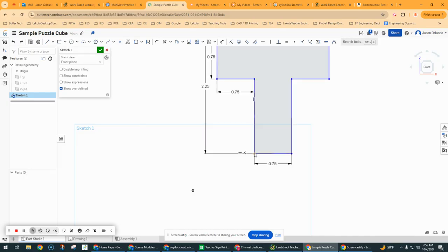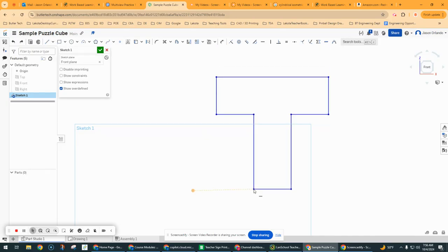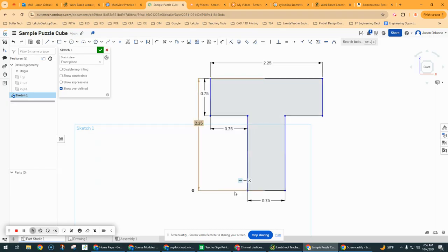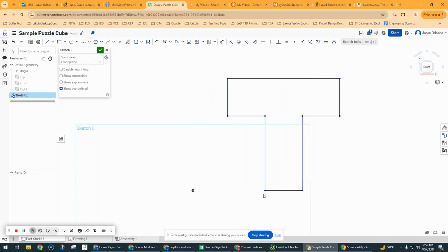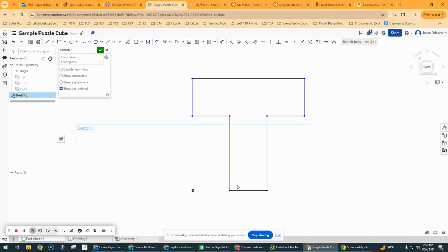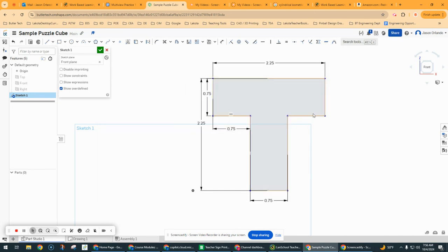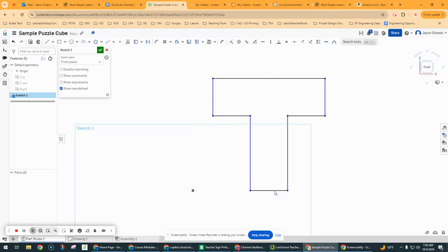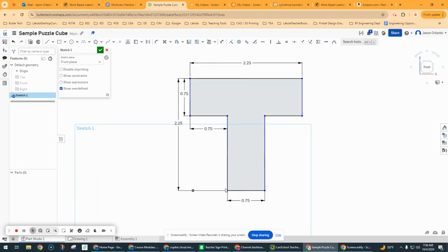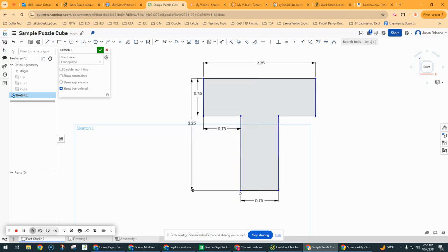Okay, now if your sketch maybe was already constrained a little bit, but not fully, right? Like if I had a horizontal constraint between a point and the origin, then I'm going to have a mix of orange, blue and black lines, because this thing can move one way, but it can't move the other. So it can't move up and down, but it can move side to side. So these black lines are kind of like, hey, I can't go up and down. I know you see the line segments moving left and right, but they're part of lines that keep going, and so those lines can't move up or down. They're kind of stuck. They can't change angles, so they feel directionally stuck.